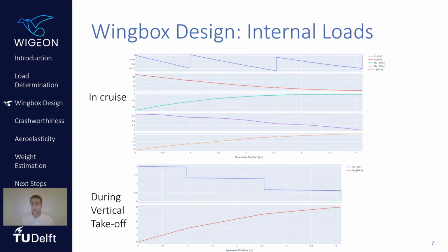Thereafter, the loads encountered in the wing were deduced, which is shown in these figures, giving the internal shear stresses, bending moments, and torques in the wing. And you can see by inspection of these figures that the loads encountered during cruise are much more critical than those during takeoff.